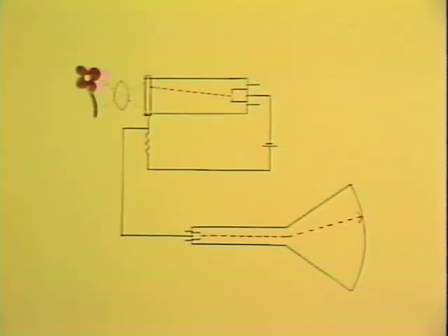The electric signal produced is now fed to the monitor, where it varies the strength of the beam in the tube. This varying narrow beam is made to scan the tube face, where it causes the screen face to glow. The brightness of the glow depends upon the strength of the beam, and so in effect the beam writes a glowing picture on the tube face.